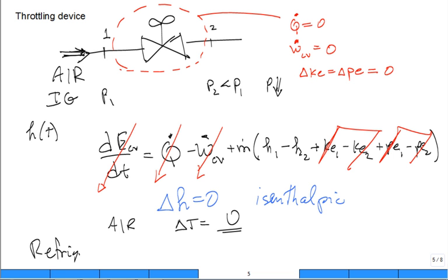And what we bring in is something that is high pressure and in the liquid state, slightly subcooled liquid. You can sometimes just bring in saturated liquid. When we put that through, something surprising happens, which throws students completely for a loop, because they say, hey, if it's no change in enthalpy, no change in temperature. True for air. You're absolutely correct for air.